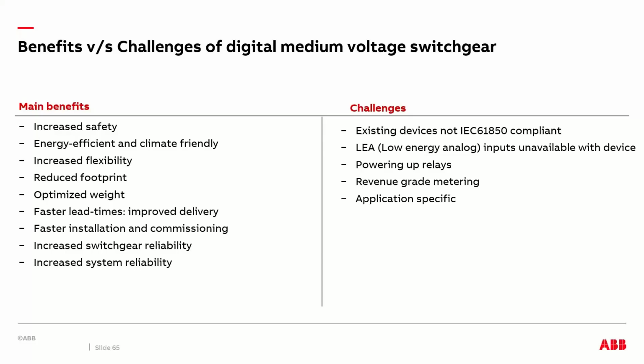Now, in practice, we see that the relays are usually powered by the instrument transformers themselves. But if we are talking about a switchgear and not something like a revenue meter, which is outside of a building, then I think this should not be such a big issue, because there will be a control power source within the switchgear for the relays to power up.